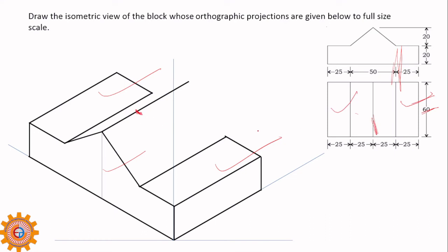Okay. So now parallel to this line, you have to draw another line. See. Okay. So the parallelogram in the top view, an isometric parallelogram, appears as a rectangle in orthographic. Orthographic view rectangle means isometric parallelogram. That's all. Drawing is over. How simple it is. So that you have to observe.